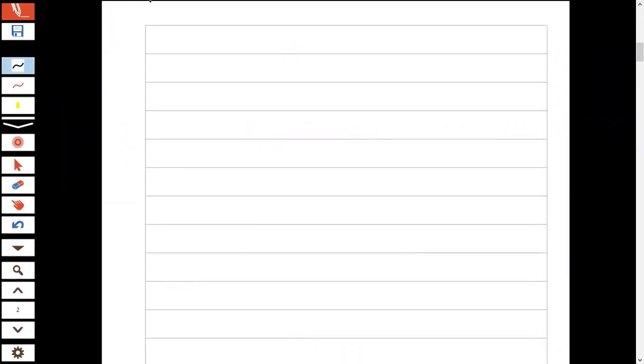So first, number two. Number two, we compute first Mu para ma-compute yung total area. Because we need to check first if it falls on the web. If it falls on the web, we are going to calculate as true T-beam. Otherwise, we'll just have the rectangular beam analysis. Mu equals 1.4 dead load plus 1.7 live load.